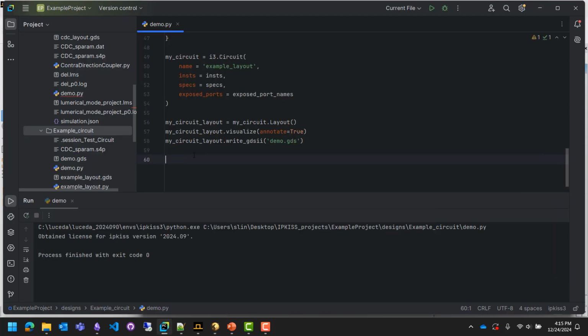So coming back to doing a circuit model now. In the same way that we did it for the advanced P-cell and the regular basic P-cell, we can also call the circuit model of the devices. And what's great about the circuit model of the whole circuit now is that you'll be able to connect all the S parameter files together so you get a realistic response of our device after it has gone through its inputs and outputs. So what I'll do here is I'll create a circuit model that will include the grating coupler, both the input and the output.